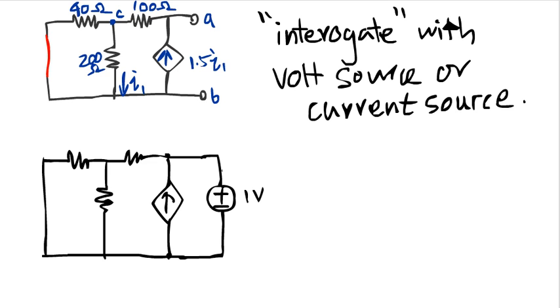And we know that the current running into this would be called Ix, and the voltage here would naturally be 1 volt. We're going to call the voltage here V1. So how do we find out about what the Ix is? Well, let's see. It turns out that the standard procedure of KCL and KVL is the best way. Now what we're going to do here is to look at this particular node here.